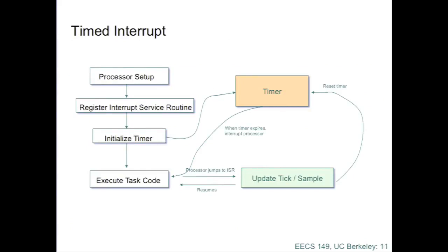All right. Now, timing. So in C, you have no control over timing. In assembly code, you have some, in the sense that you can sometimes count instruction cycles for simpler processors, but not reliably, because if one of your instructions reads a memory location, then how long it takes to execute that instruction depends on whether you've got a cache miss or not, right? So even if you're looking at assembly code, it can be pretty difficult to know the timing. So when you want to do time-dependent actions in a microcontroller, you typically use an external piece of hardware called a timer.